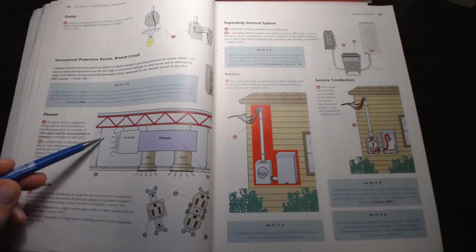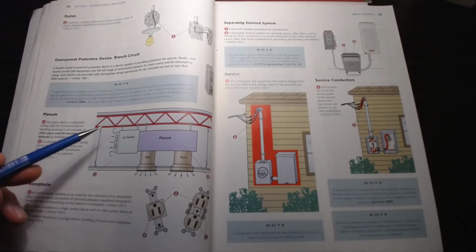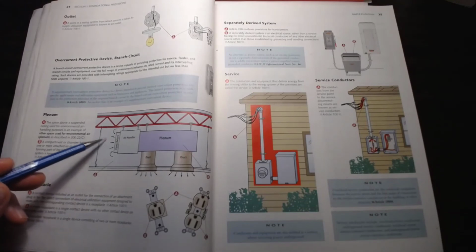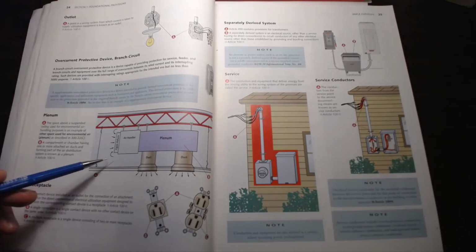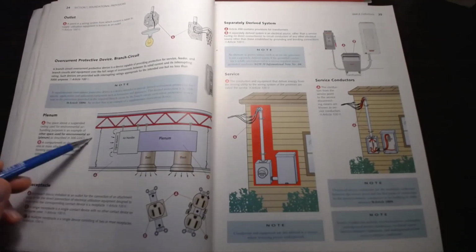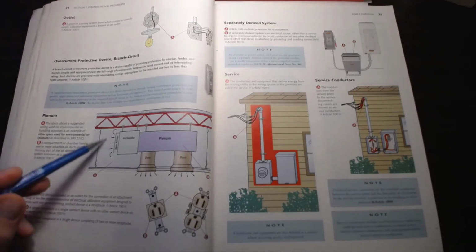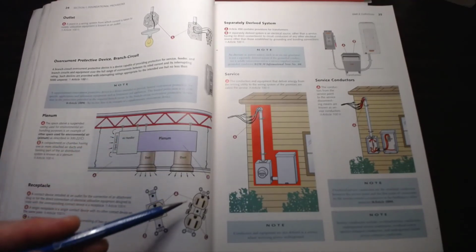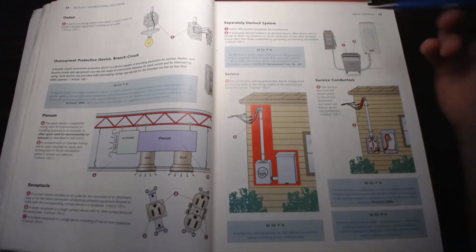Now the reason is, since this is environmental air, you could present a hazard by putting the wrong type of, say, Cat5 cabling or wrong type of electrical wiring in this plenum space. And if it were to catch on fire, then it would produce toxic smoke that would then be sucked into the air handler system and moved through. So it's important that we know that.